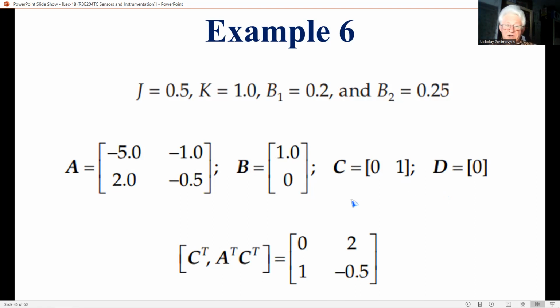Normally, it is more difficult to measure torque in a shaft than speed, particularly when the shaft is rotating. So in the present example, suppose that we wish to estimate the torque in the flexible shaft when the input speed is 2. The system is observable or constructible because it's non-singular, as you may see at the last expression here.